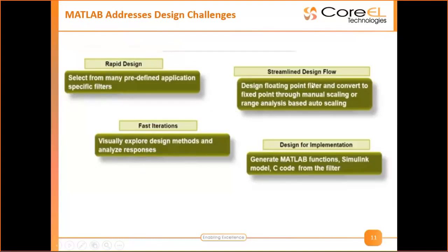For a streamlined design flow, MATLAB also has Fixed-Point Designer, which converts your floating point data to fixed point data, which is what actually works in the hardware. Like we know, whatever hardware we use, everything inside, whatever data is processing, is fixed point. Even in a laptop, it is fixed to around 64 bits. So all the iterations should be fixed to a specific word length so that the hardware supports it, and when you're processing, there is no overflow, no loss of data, and no corruption of the data.